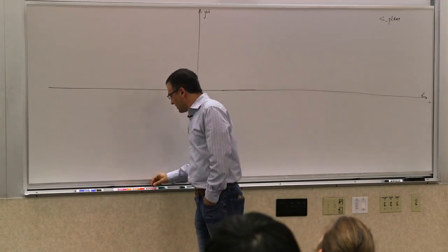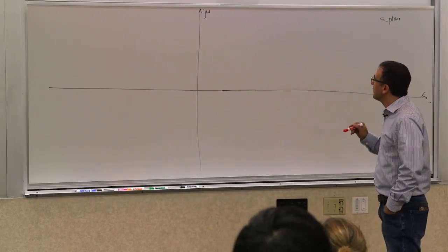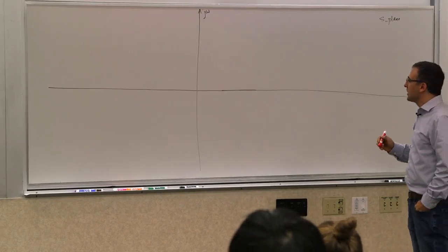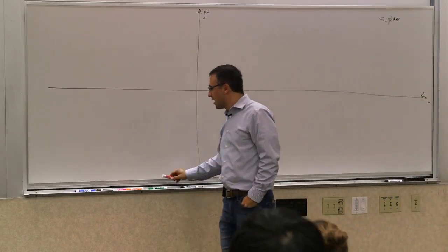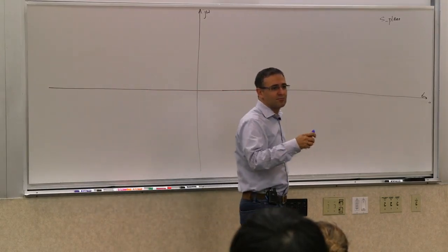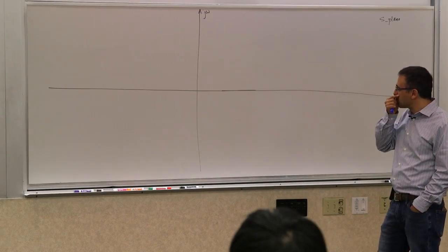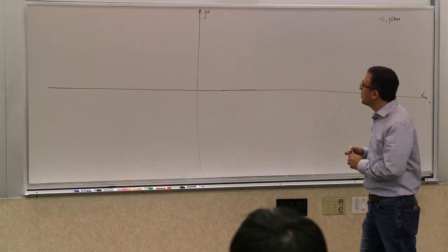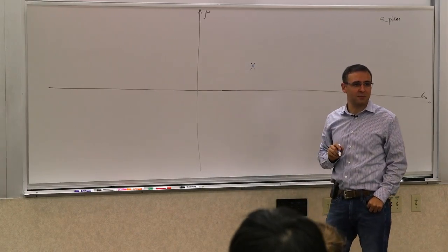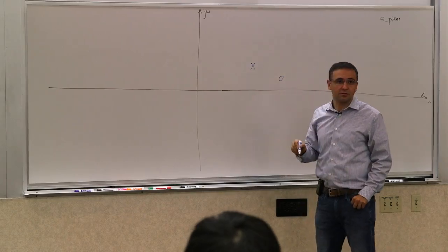Okay. So now let's start with something very simple. What we are trying to do is to find the impulse response. So what we are showing is the impulse response of a system with certain poles, starting with the poles first, and then we'll see how the zeros get into the equation. By the way, we show the poles with x's. So if I put an x here, it means that the system has a pole here. And we show the zeros with O's, like zeros.